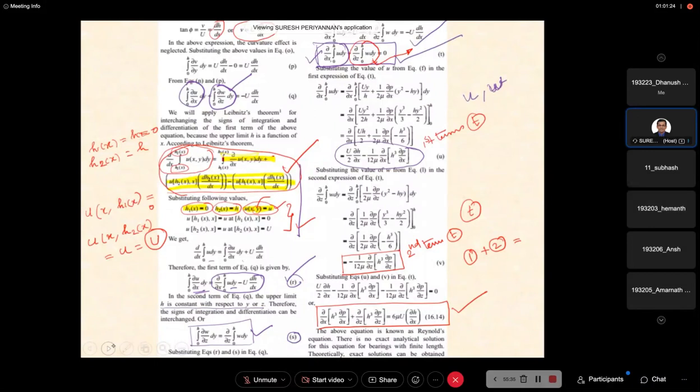Here the pressure is the bearing pressure, a function of x, y, and z. The velocity we can easily evaluate in all directions. Velocity of the fluid element. Fluid element in that sense, which element we considered a lubricant element with respect to bearing pressure.